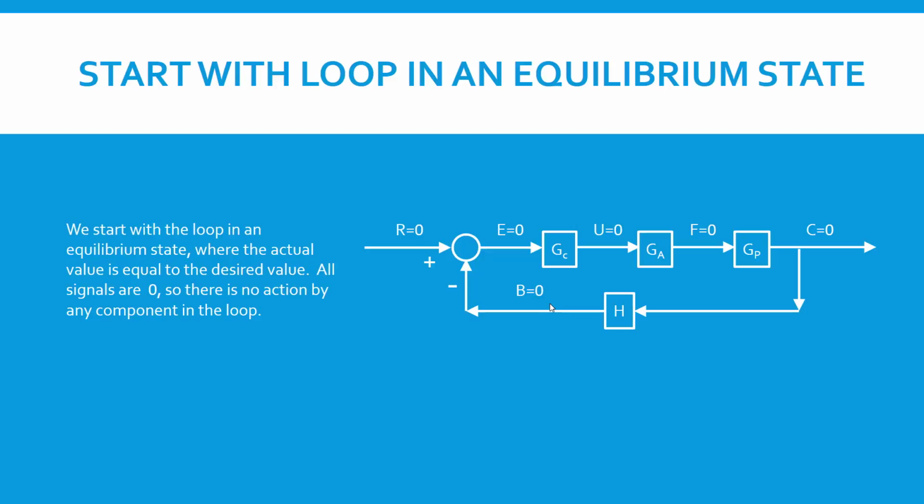And when we compare the desired value with the measured value, we wind up with zero error, which goes into the controller. The controller receiving a zero, that's a message basically to do nothing. And so it does nothing. It sends a signal, basically do nothing, to the actuator, and the actuator responds by not doing anything. And so the system just continues to sit at whatever state, at this equilibrium state. The message inside the loop from one component to another, from every component to the one that it's connected with downstream, is basically don't do anything.